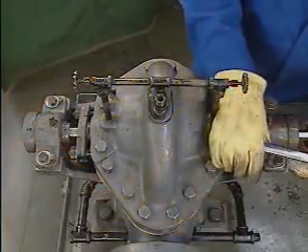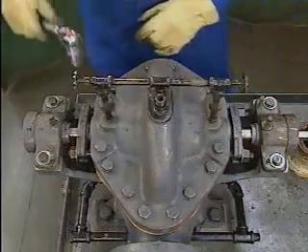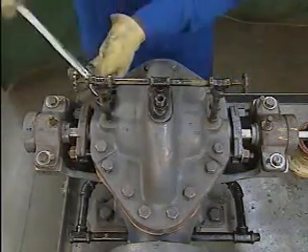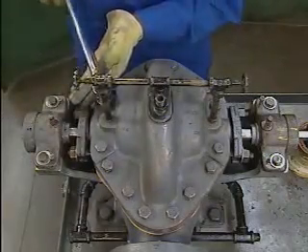He will repeat this pattern several times, gradually increasing the tightening pressure in several stages. If this tightening process is not followed, the sealing surfaces could warp, or the gasket could be improperly compressed. Though all tightening sequences generally follow a crossing pattern, not all tightening sequences are exactly alike. The number of bolts and the shape of the flange dictates what the exact sequence will be.